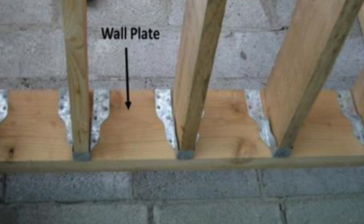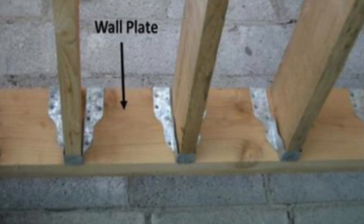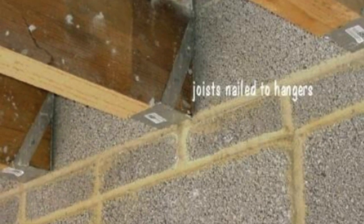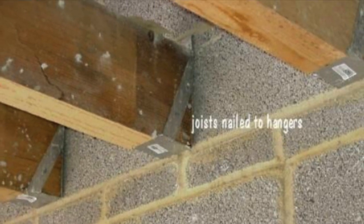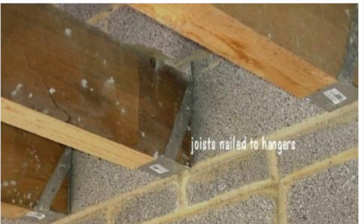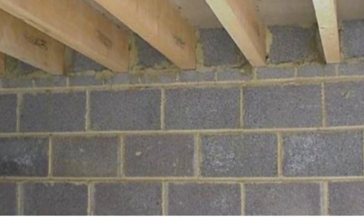Floor joists, or some may call it ceiling joists, I think it depends on how you look at it. It is similar to suspended timber ground floor in terms of the function. But for timber upper floor, joists can be rested on the wall plate by using hangers, hanger nails into solid wall to support the floor joist, or the end of the joist could be built into the wall.